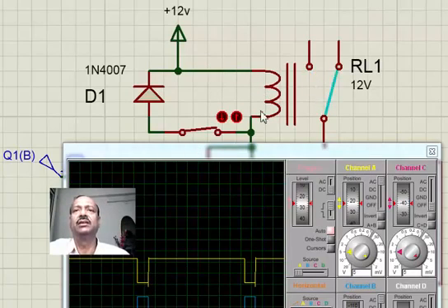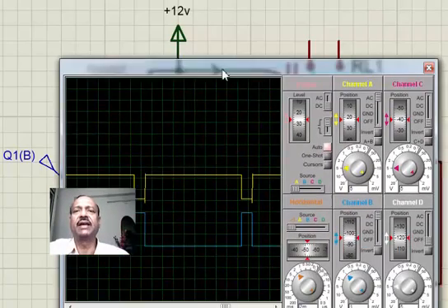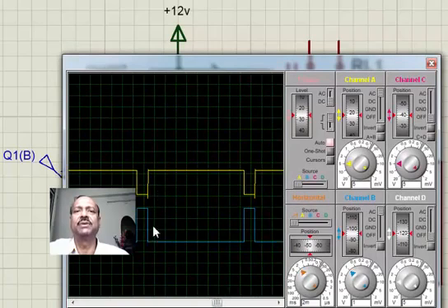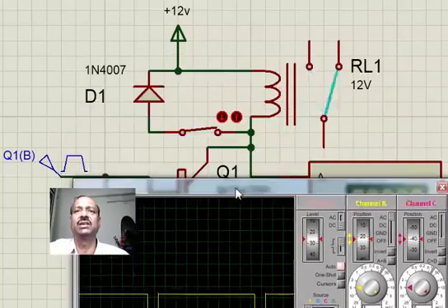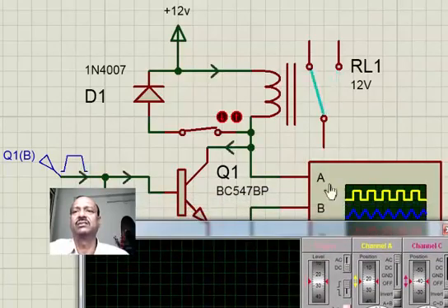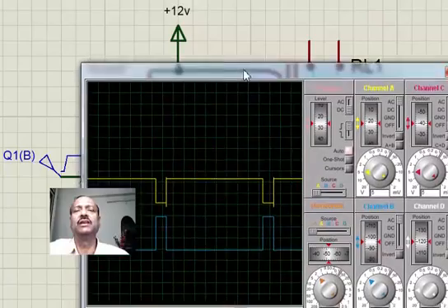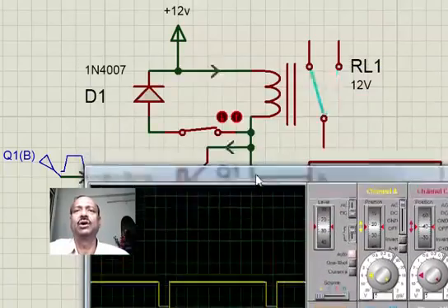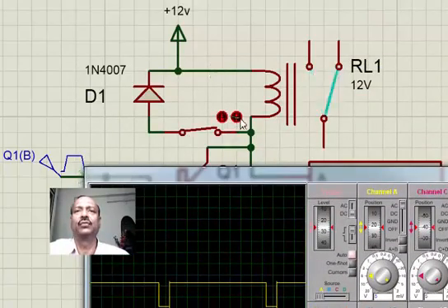The current in the off time will start flowing through this diode, and that is how the voltage spike which was otherwise appearing across the transistor is avoided, because the yellow one is connected across the transistor, as you will see, and the transistor will eventually fail if it is not able to withstand that kind of voltage.